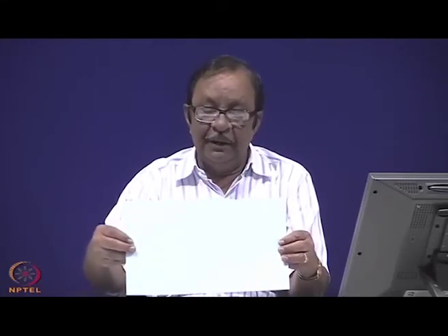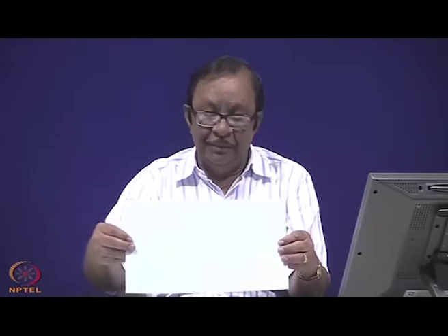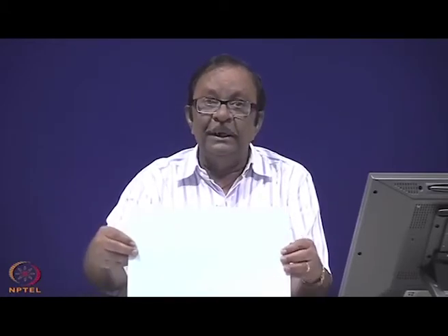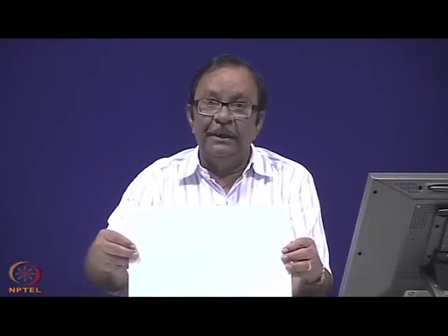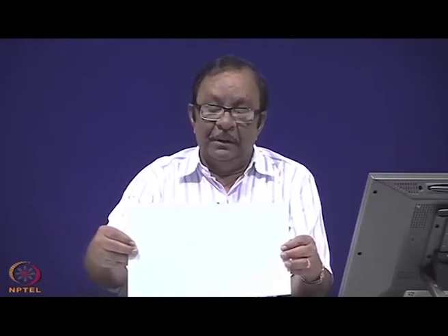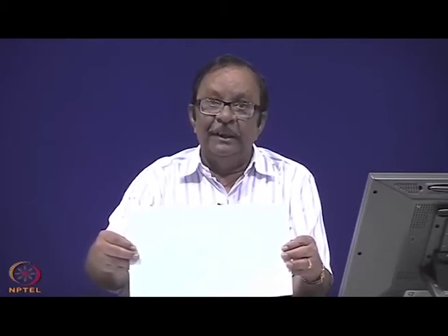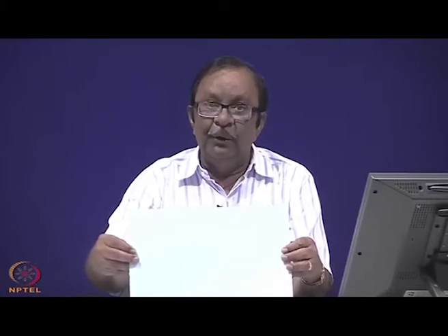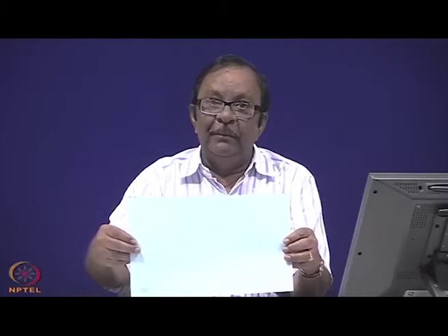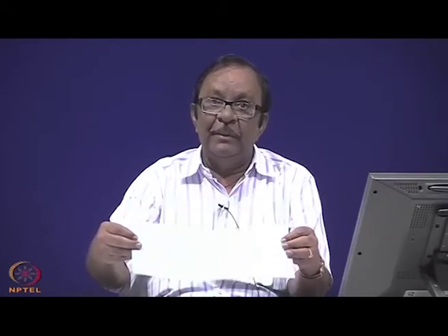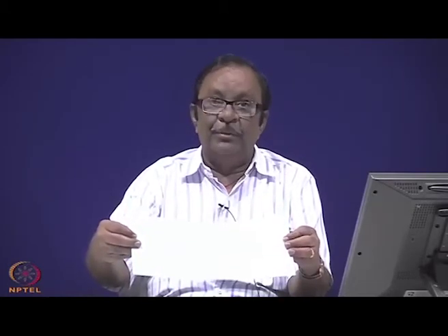So, I make one simple adjustment per day, that means the slope beta is chosen such that the sun's rays are normal to the plane at solar noon. For example, in December when the sun's rays will be pretty low, I will have a higher slope, and in summer it will be a steep sun, so I may have a lower slope.